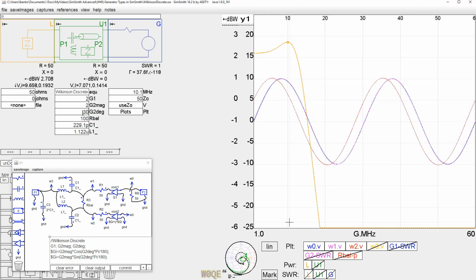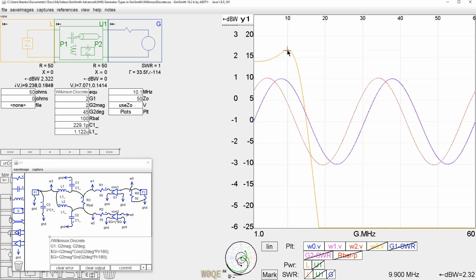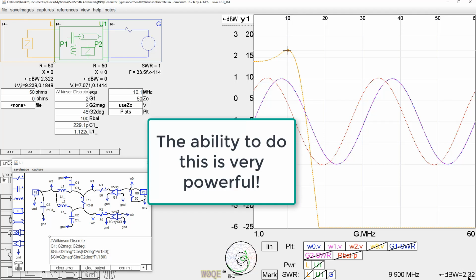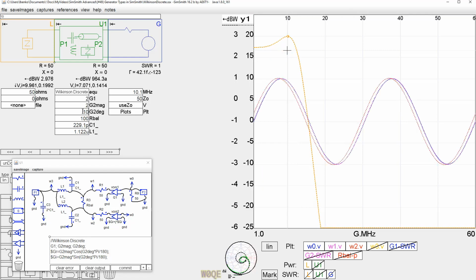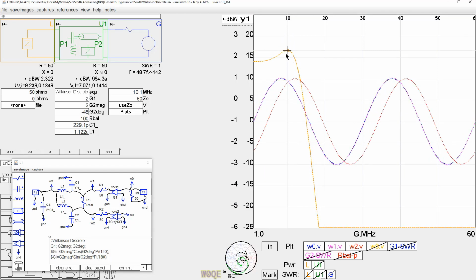changing the phase of it, and we can see the power coming down. So by the time I get to, say, 45 degrees, I've lost, I went from 3 dB to 2.3. I've lost 0.7 dB. And it would be the same on the other side, I'm sure. It'd be symmetrical on both sides. Same value again. So here's a case where we needed extra generators.